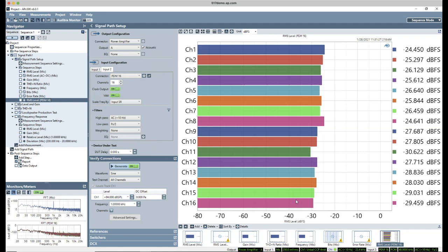Now I am reading some different sensitivities on the other microphones, and those are generally trending down. There is a little bit of ambiguity here. The tolerance on these microphones is plus minus 3 dB. So there's some of that going on, but also my sound source is sufficiently close, it's only a few centimeters away, that I'm seeing the effects just of distance, the decline in sound pressure level with each doubling of distance. So there's some of that going on here.